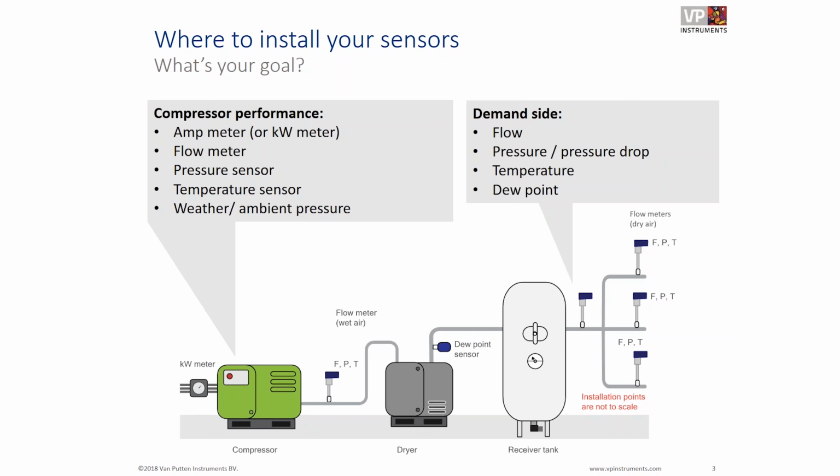And well, today I was actually at the gym, and I was on this air-driven rowing machine, and I figured out they had just cleaned that machine, because I had to use much more muscle power at the same position as last time. And it's just like with turbo compressors. If the inlet is a little bit polluted, then there's less air coming in, and you will see that the amps of the motor, the current consumption, will drop a little bit. So I had this very nice experience today while being on a rowing machine.